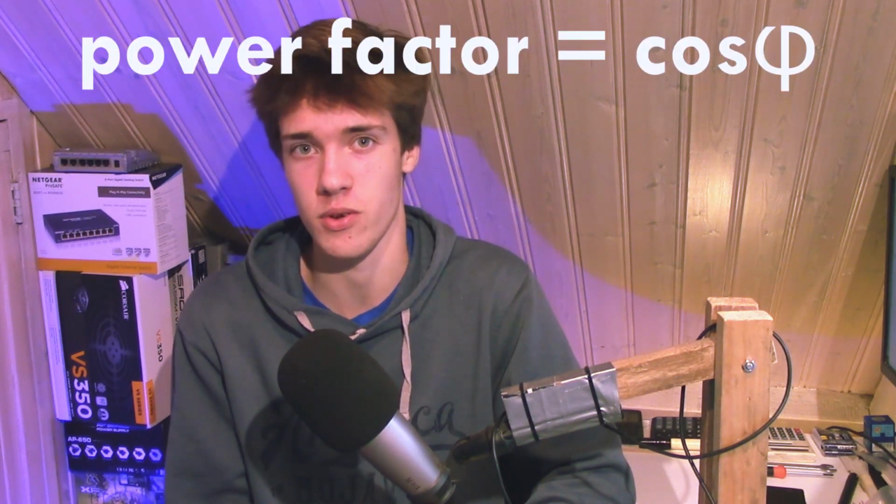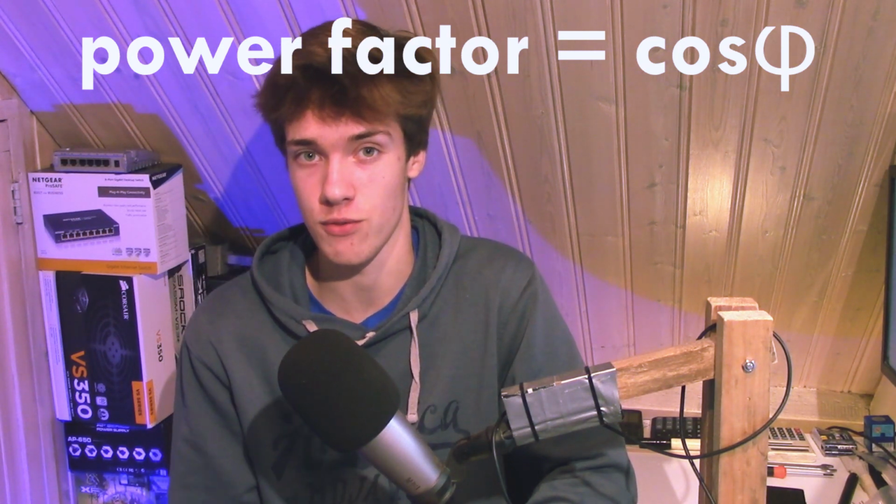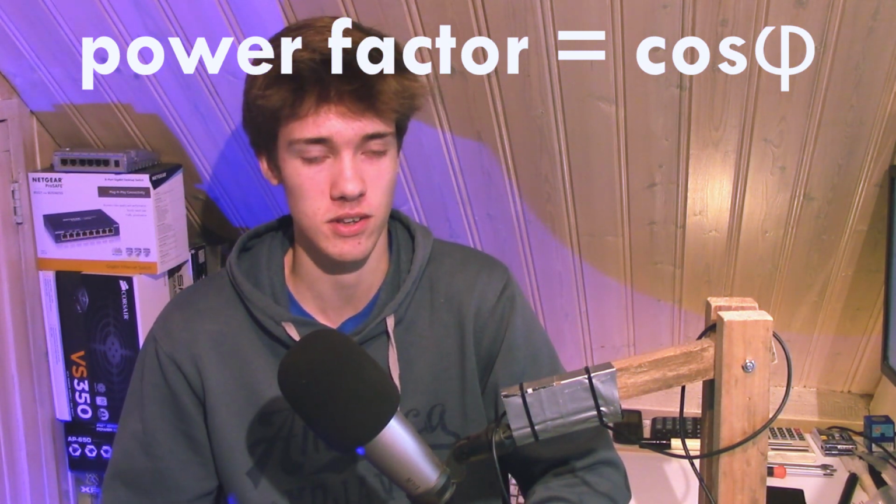Right. We've investigated that. And so I can hear you thinking, well, that's all very nice, but how do I even know this power factor? You know, the power, yes, sure, I need to multiply the apparent power by the power factor, but how do we find the power factor? Great question. The power factor can be found by taking the cosine of the phase difference between voltage and current. It sounds very mathematical, but it actually makes perfect sense.